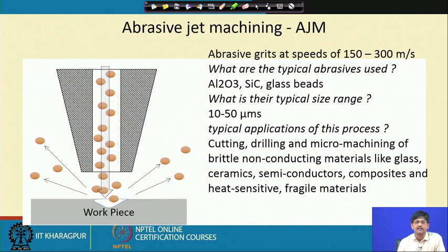One very common application of abrasive jet machining is that suppose there is a pipe and internally there are some burrs sticking out and creating some obstruction to the flow which you intend through that pipeline. An abrasive jet nozzle can be put inside that pipe to remove that burr extending inside the pipe, which other processes cannot practically carry out.